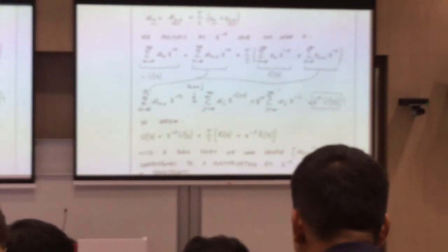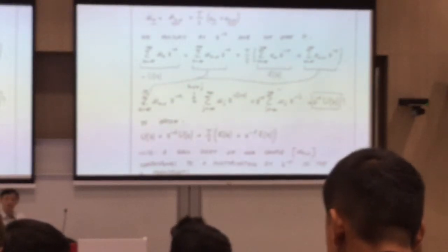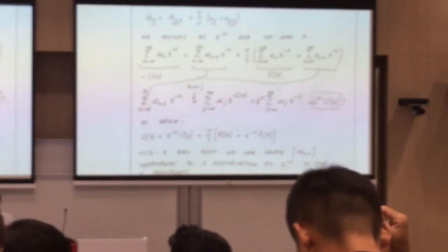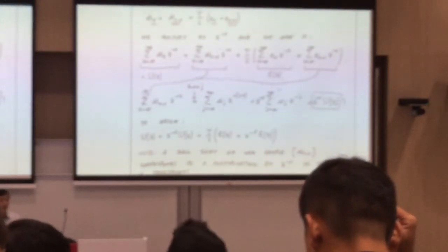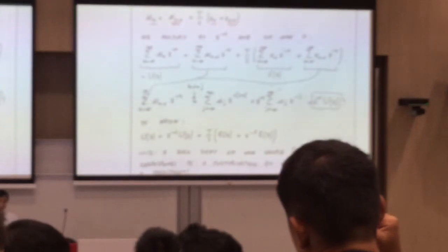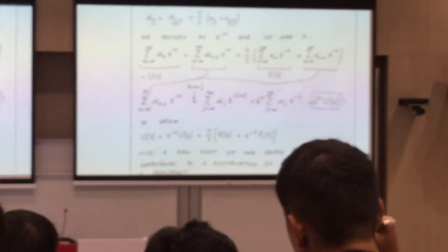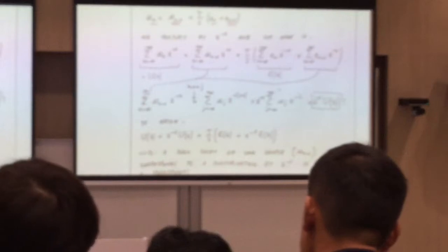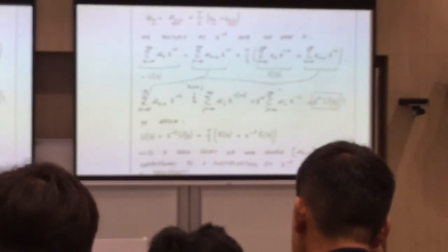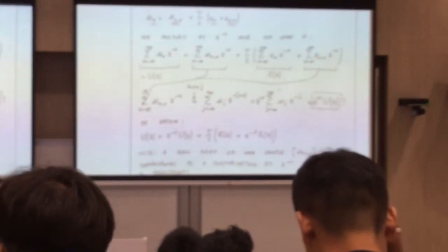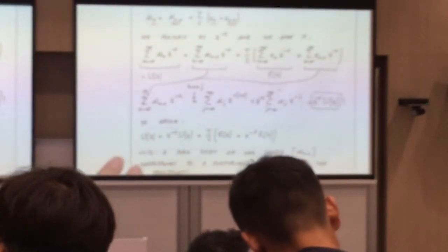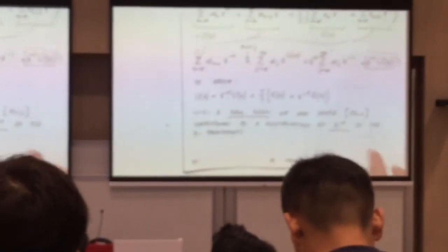The Z transform is similar. Before the Z transform, you got 1 delay, 2 delays, 3 delays, 4 delays, n delays. You got n independent delays, and that is very difficult for you to solve. But after we obtain the Z transform, instead of so many independent time delay variables, we only have the Z variable. We convert all the time delays into polynomial functions. So any back shift represents Z power minus 1, and of course any forward shift will be power Z.